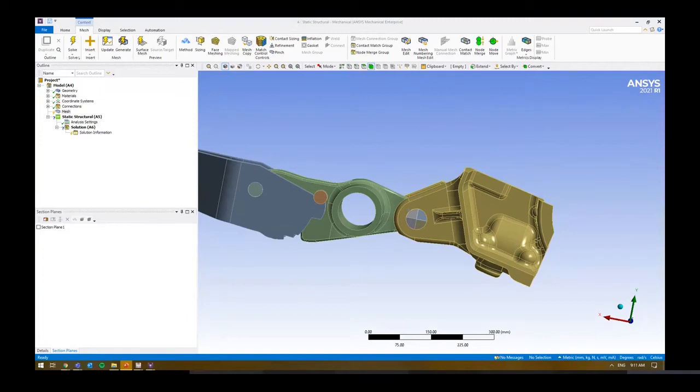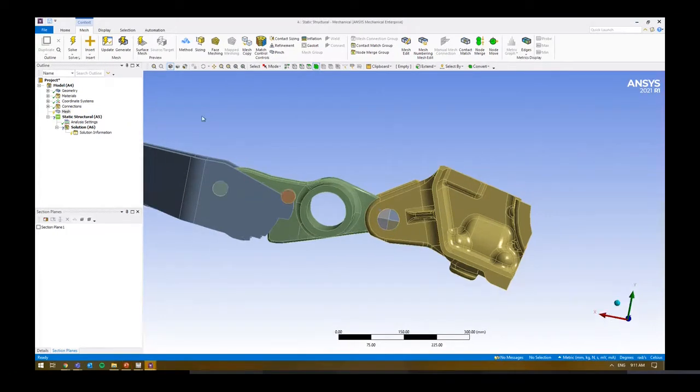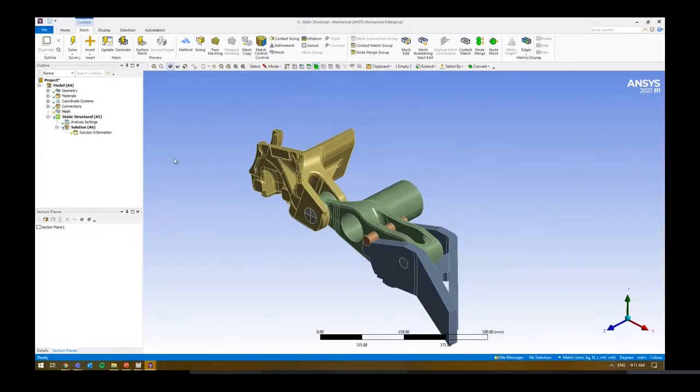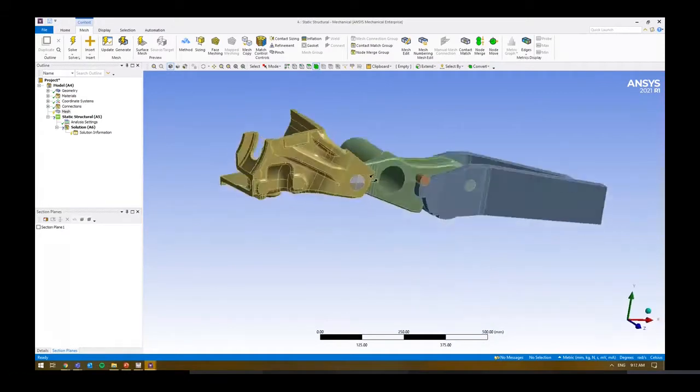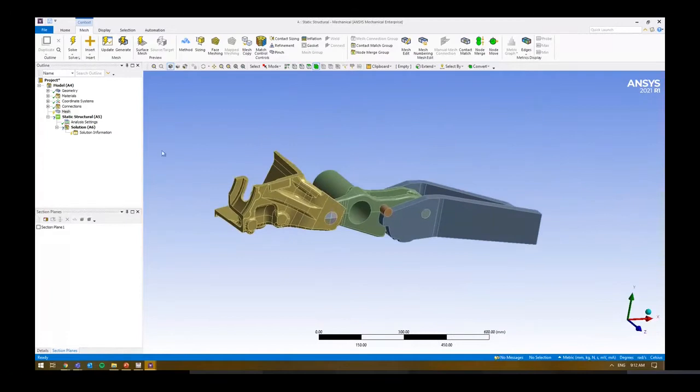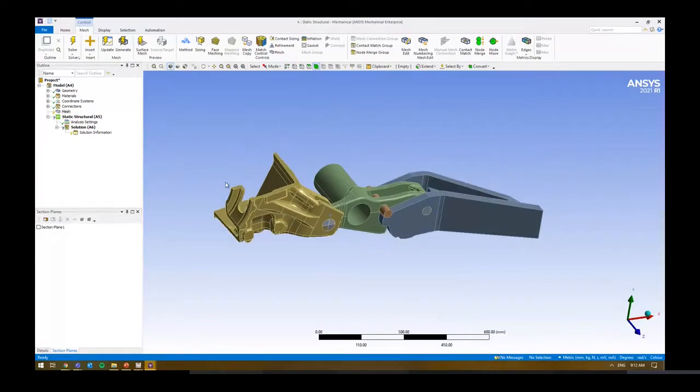So what we'll do, meshing geometry. We'll play around with this and start to talk about what we can do with meshing. The whole reason we're generating a mesh is that we're going to perform our stiffness calculations on the actual mesh, and the mesh quality and size will be very important when it comes to picking up the accuracy of the model.